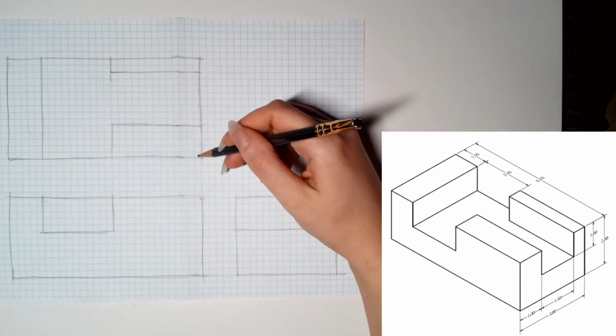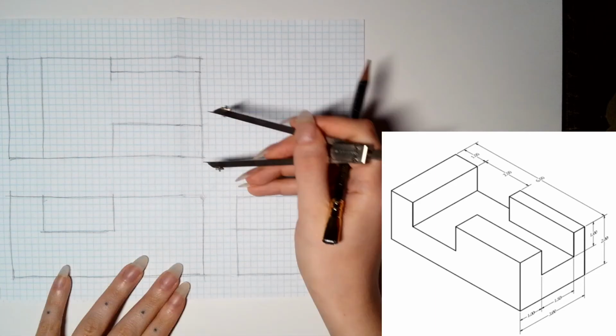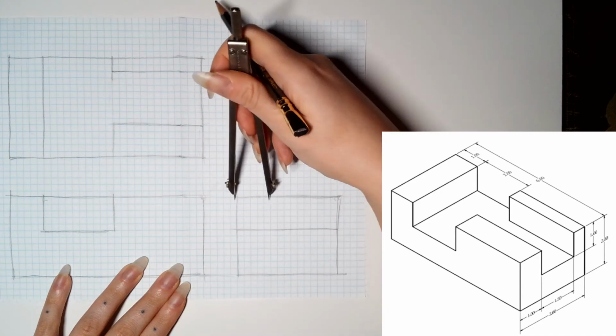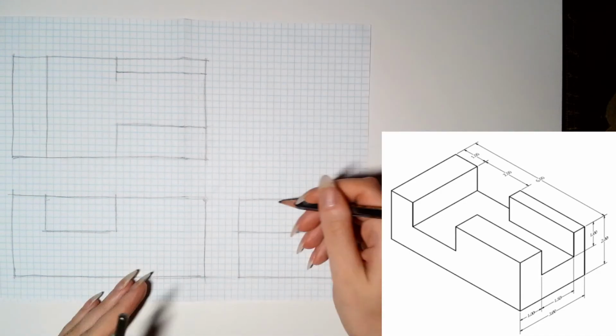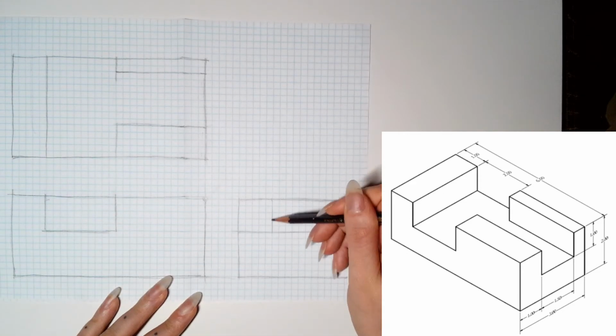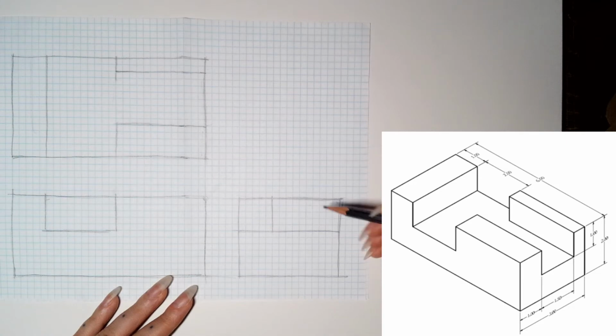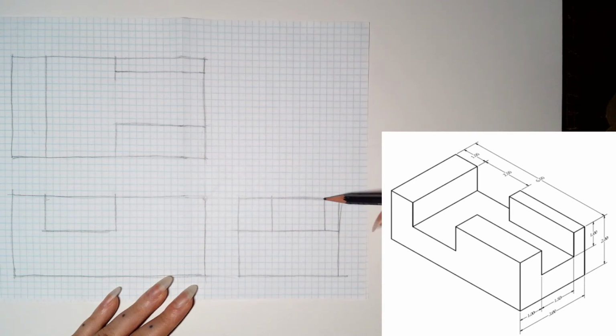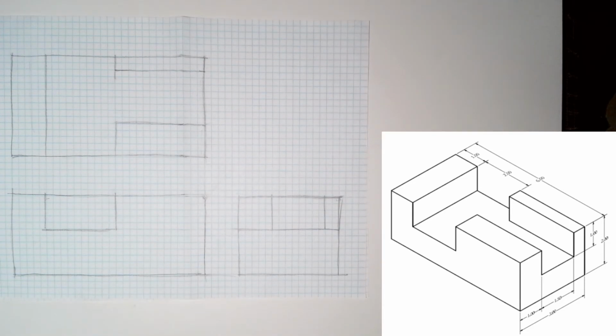So again, I could just say, well, it's 5 boxes, or I could use a divider to measure it over. Or if I didn't have one of these on hand, I could use a ruler to say, well, that's 1/2 of an inch, and then measure over 1/2 of an inch and project it down. And again, if you wanted to look at the video from last semester where I have all of those technical measurements, you could see that happening.